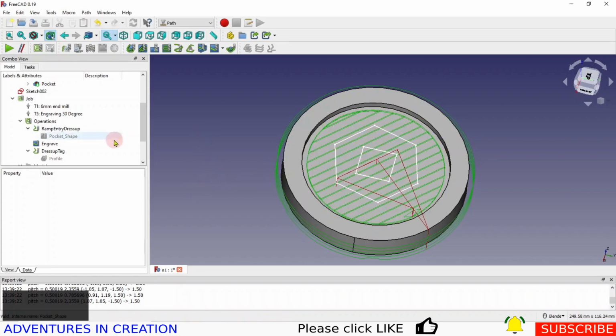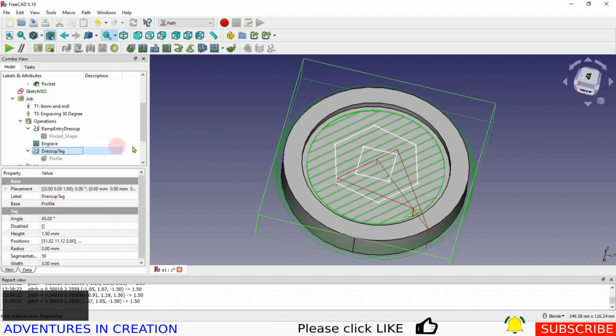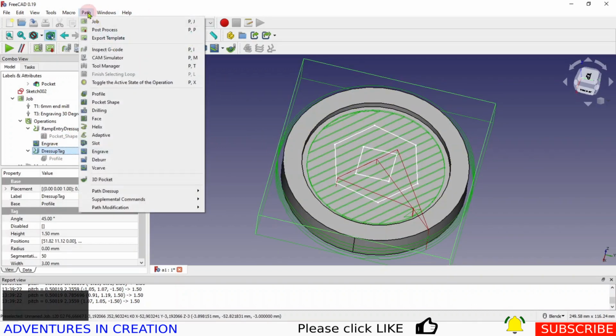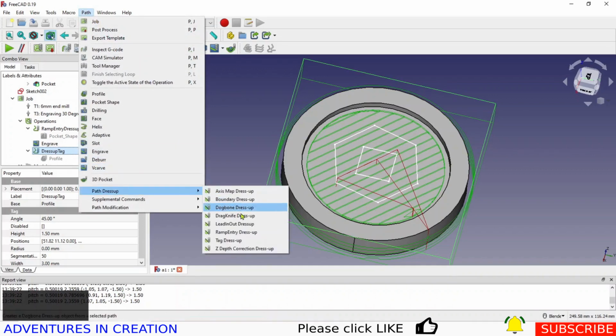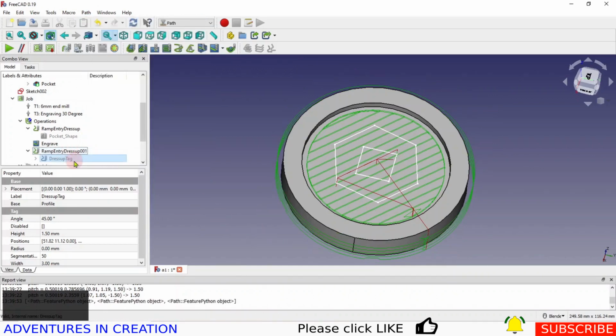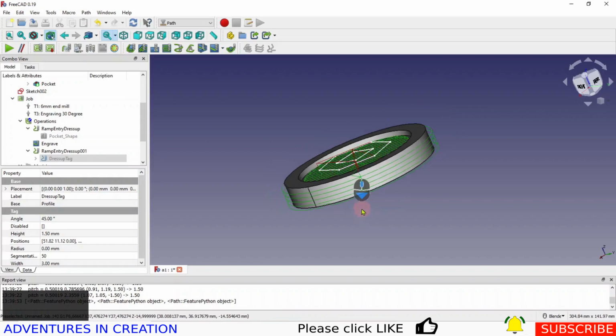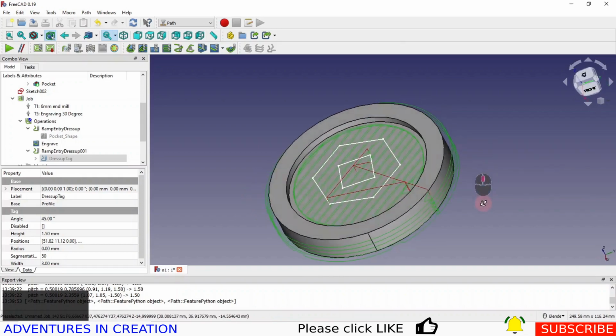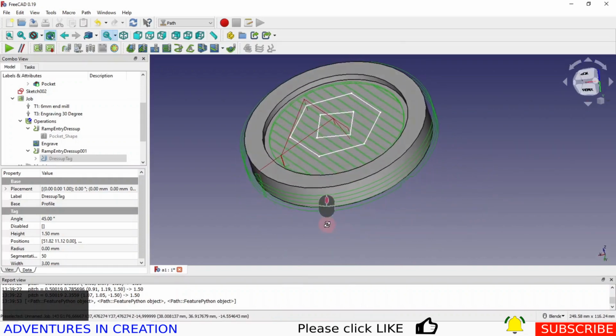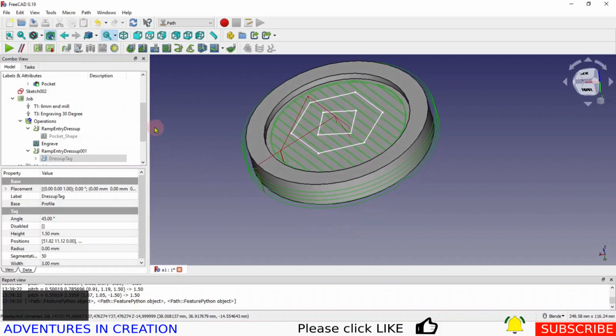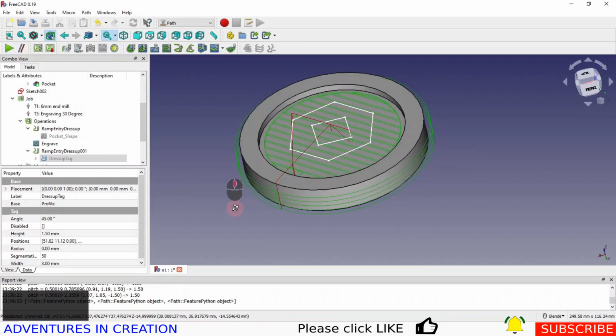Now we want to also apply a ramp entry dress up. So it's as easy as picking the dress up tag, path dress up, ramp entry dress up. And now I have the ramp entry dress up. So if you look here, you can see where it's going to ramp in. So we don't go straight down, we're going to go in at a bit of an angle. And that is basically it. That's all we need to do to make our part.